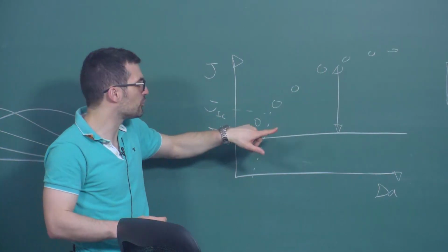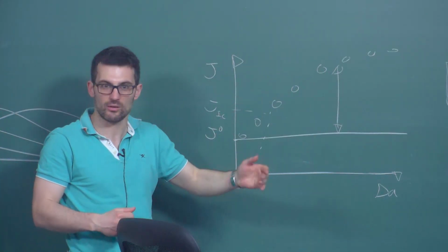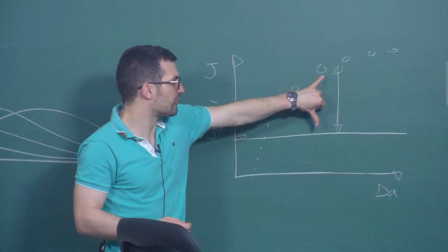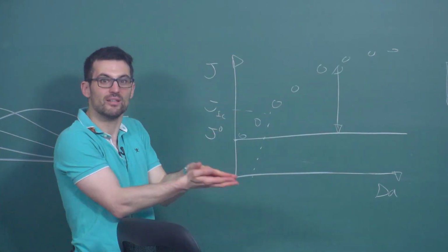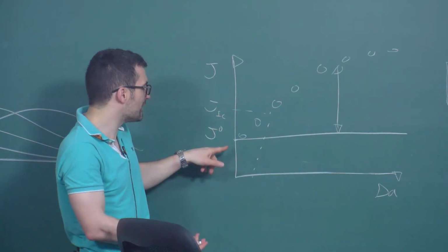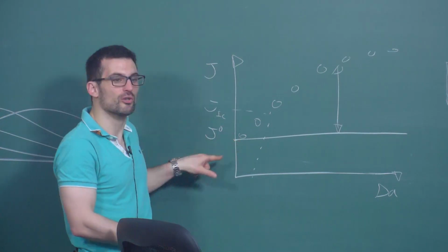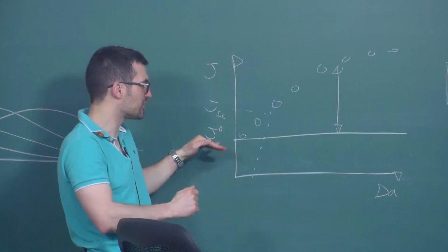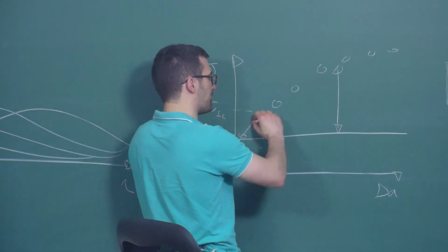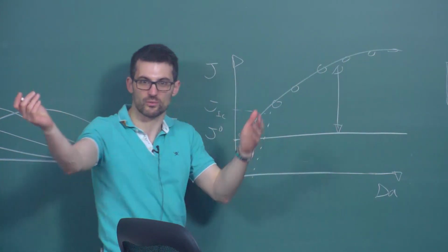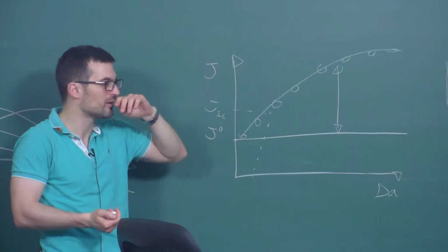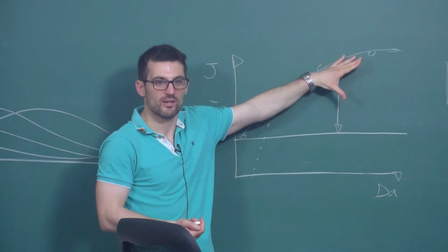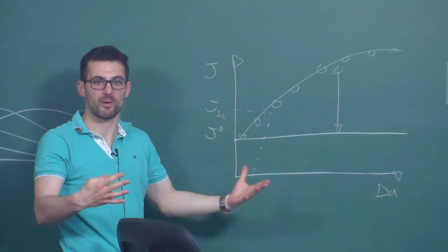So anytime you run a cohesive zone or phase field model, you capture the toughening, because that comes from the bulk, not from the interface, from the cracking. So in the cracking, you could keep your GC constant. In this cohesive zone model, the gamma 0 remains the same. Or in phase field, you keep your GC constant. But your model will naturally predict this thing. We saw some R curves when I was talking about, for example, the pipelines and so on. Your model will actually predict this thing because this is the plastic dissipation that is happening in the bulk.